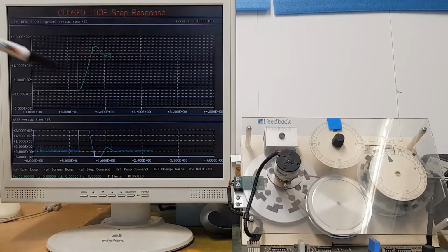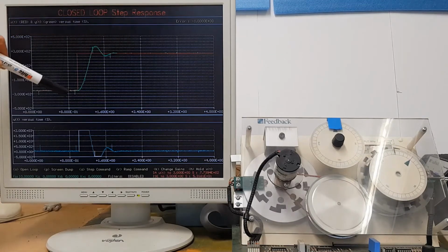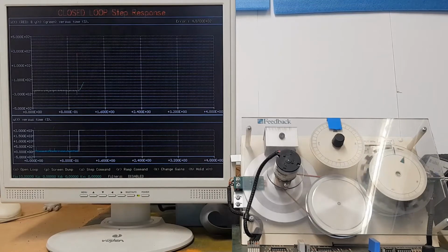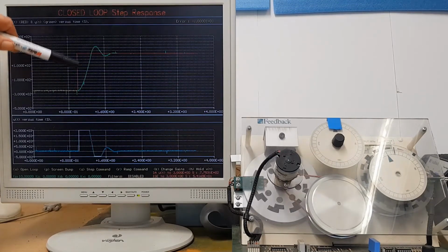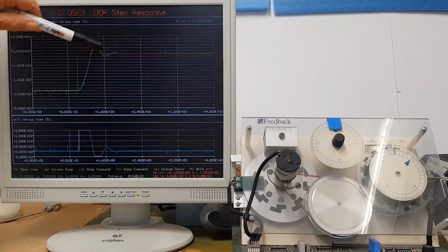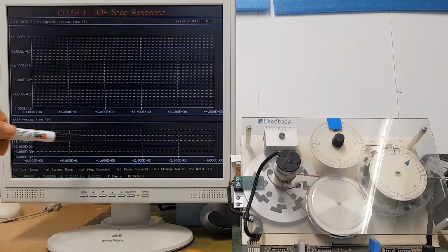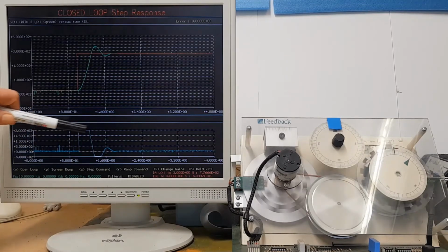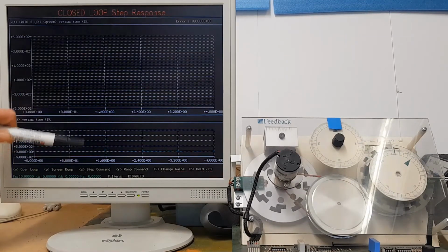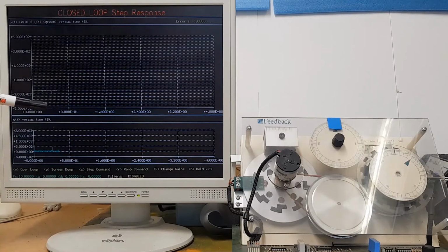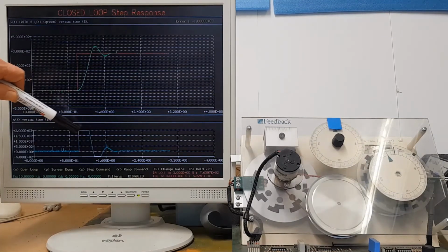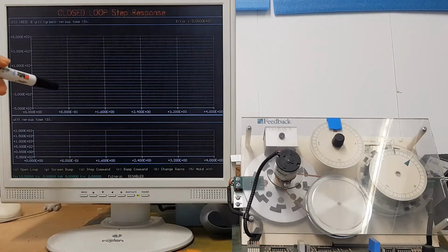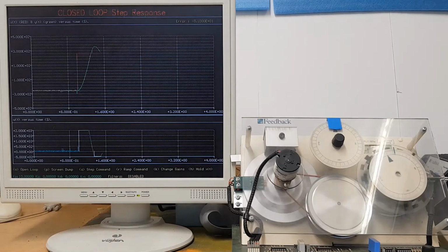Look at the screen. The red line is the input, sorry, and the green line is the actual potentiometer. So this is the desired value for the potentiometer. This is the actual value of the potentiometer, and the signal down here is what voltage we're applying to the motor. Now this can be limited because it can only go plus and minus 15 volts on this particular motor. So if it hits the 15 volts, it means it goes along that line there, which means the motor's saturated.